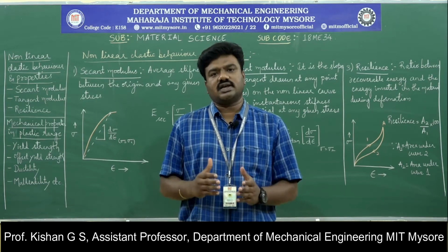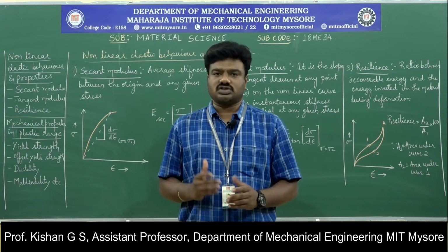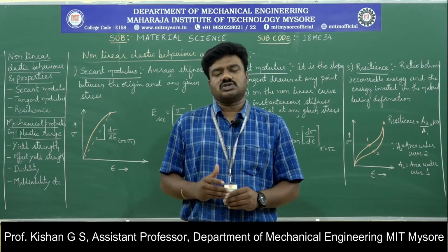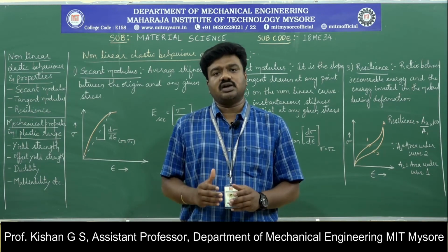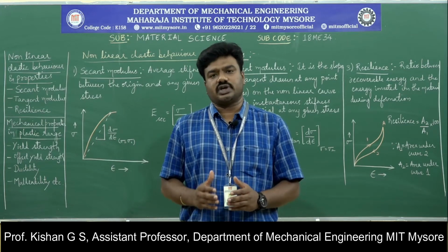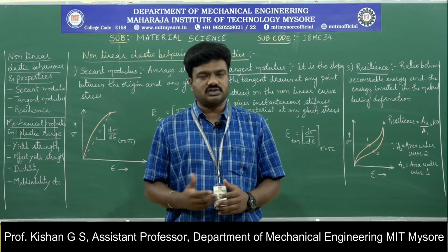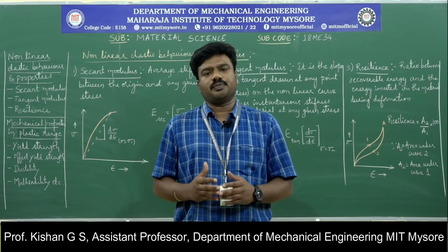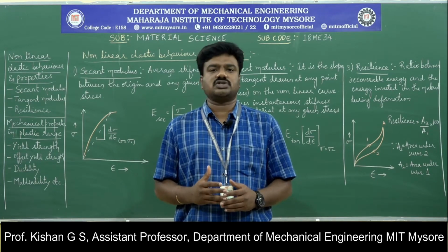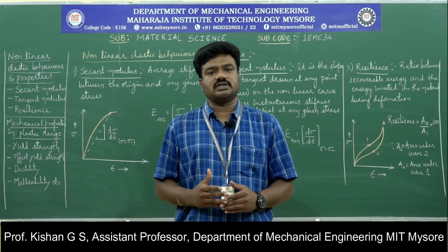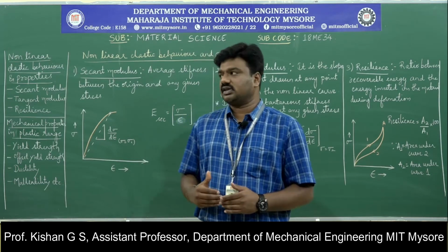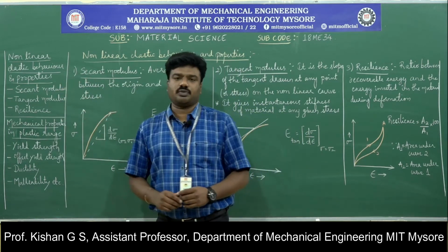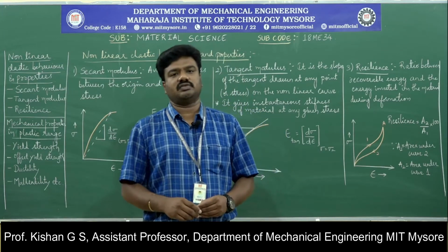Coming to these elastic and plastic regions, we have two concepts as well. In the elastic limit itself, we have linear behavior and non-linear behavior. The linear behavior applies when the stress is directly proportional to strain. In the curve we studied in the previous session, the limit wherein the stress is linear to strain, the properties defined in that limit are called linear behavior or linear properties in the elastic limit. Whereas in this session, we are going to deal specifically with the non-linear elastic behavior and properties of the material under the mechanical behavior topic.